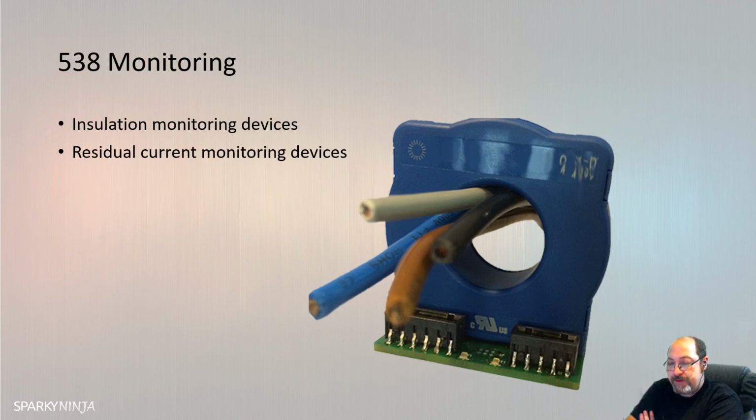It will be connected symmetrically or unipolarly between the live conductors and earth, or the protective earth connections or reference point for the protective equipotential bonding. Where the neutral conductor is not distributed, the line terminal of the IMD will be connected to either an artificial neutral point within the three impedances connected to the line, or to the line conductor.